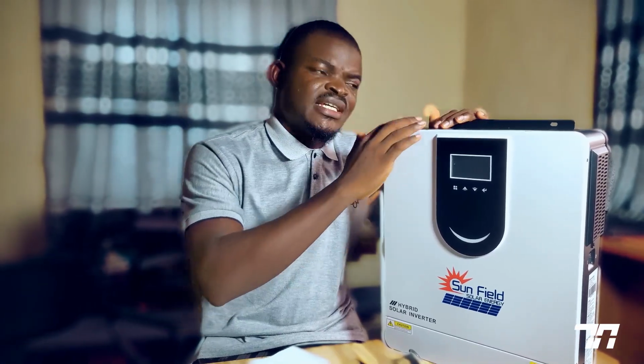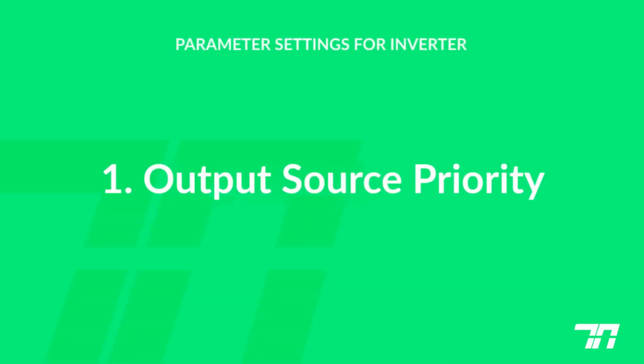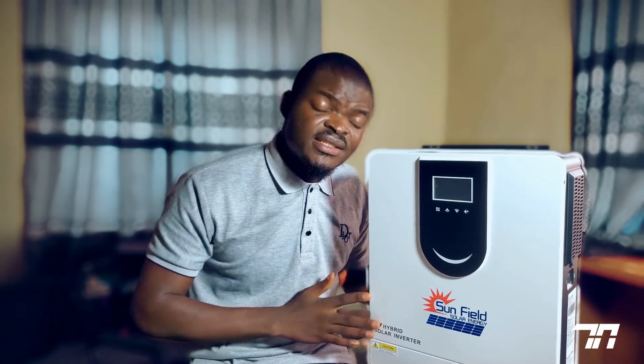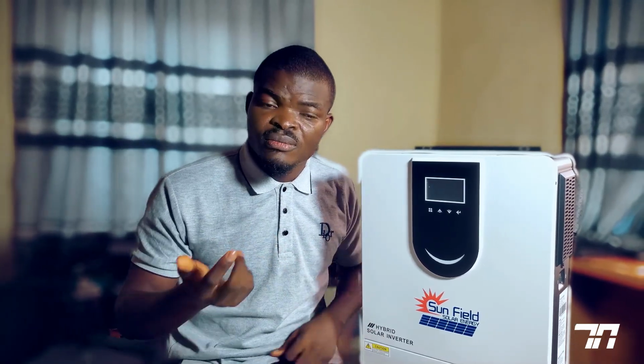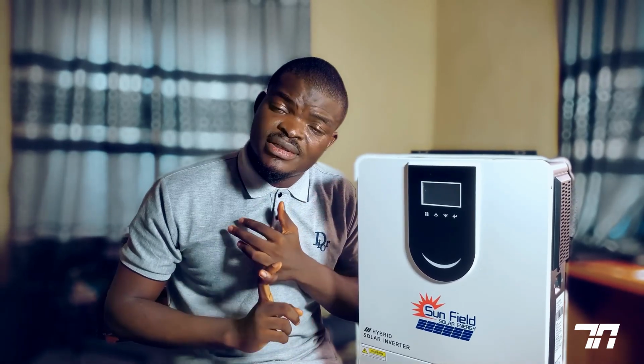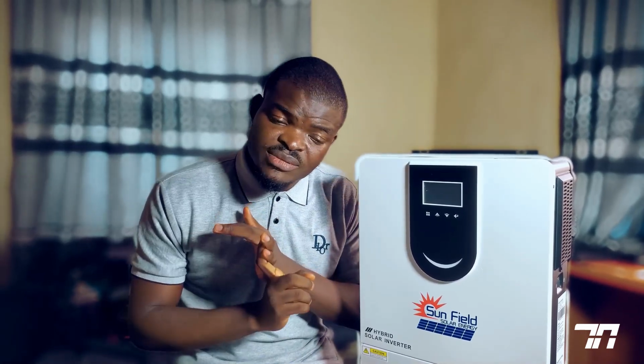So what are the parameters that need to be set? Number one is output source priority. You need to set your output source priority regularly. All of them used to have, I think, about 3 to 4 priorities. One of them is solar priority. Another one is utility priority. The first priority, utility first.